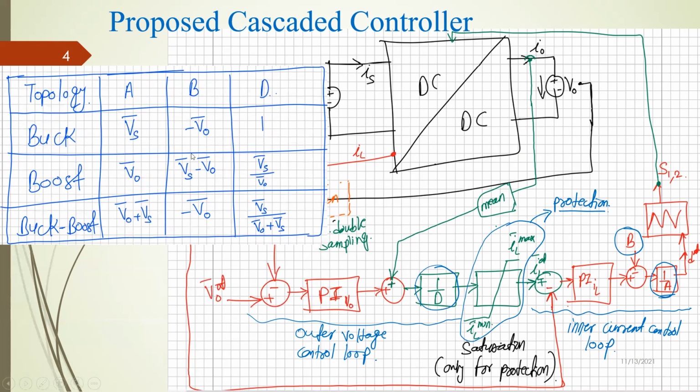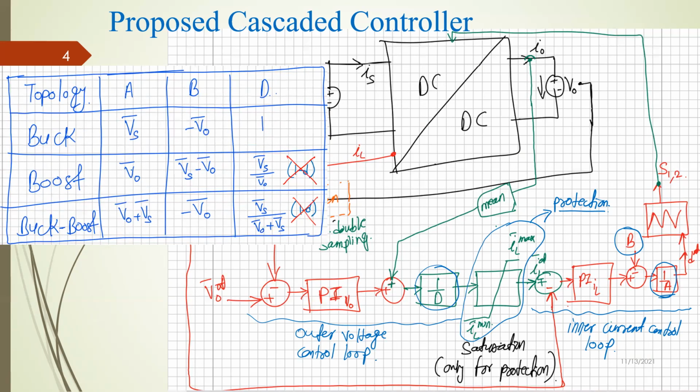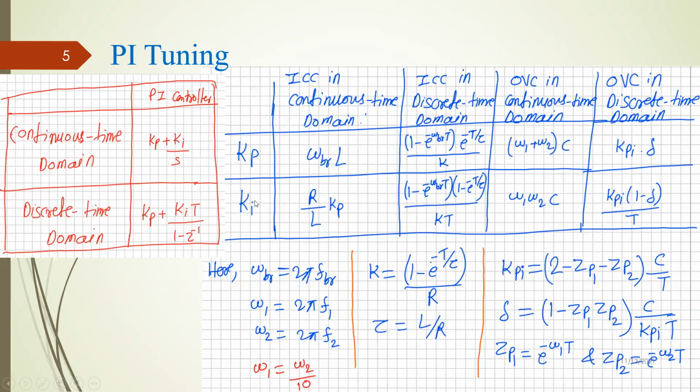If you have watched the first three videos, you would know how these expressions are obtained. But I would like to mention that in the third video, we also said you can compute this capital D using 1 minus T, but we do not want to use it. We don't use this because it introduces coupling between the high frequency, faster current control loop and the slower outer voltage control loop. It introduces interaction between them, and hence it makes things worse, and the performance will be bad. You can also try that in the Simulink model, which I have already downloaded, and see how it looks.